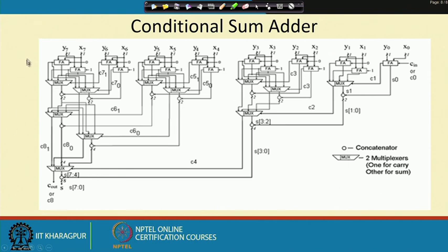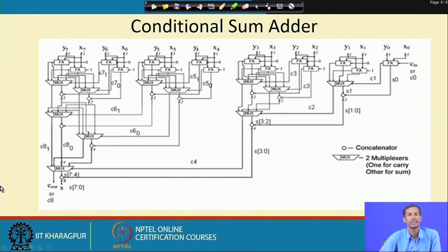For this, next to next, it will follow something like this, then again like this, and then again like this. So, that means 2 3 4, 2 3 4, it will continue, and finally this carry will select the final output bit. As I am following these 3 levels at the maximum on the MSB side, for the 16 bit, for y 15 and x 15, along with y 14 and x 14, I will get 4 levels of multiplexer over here.